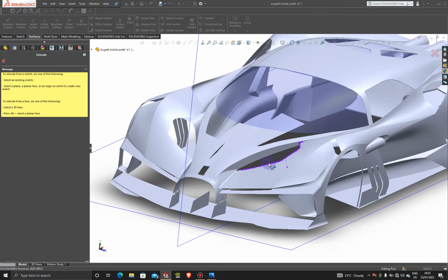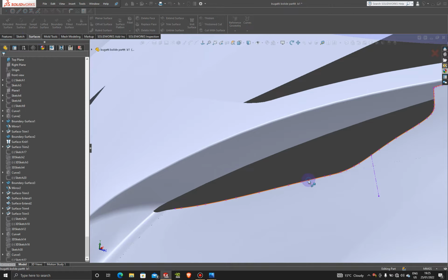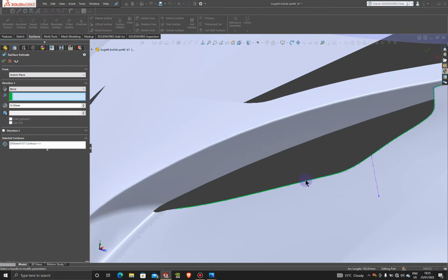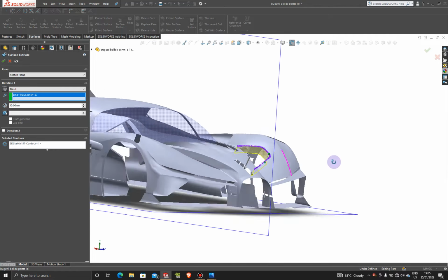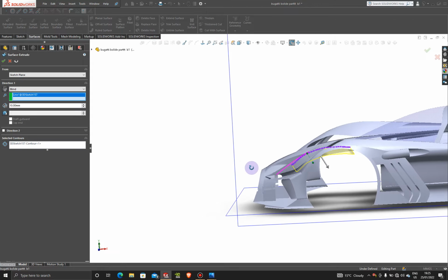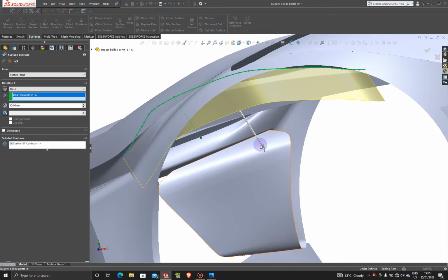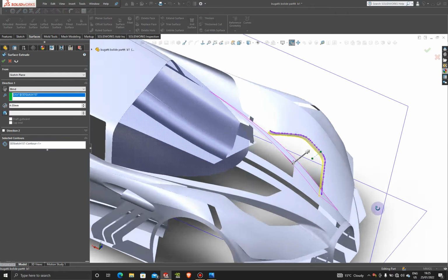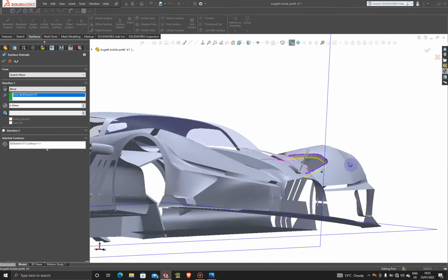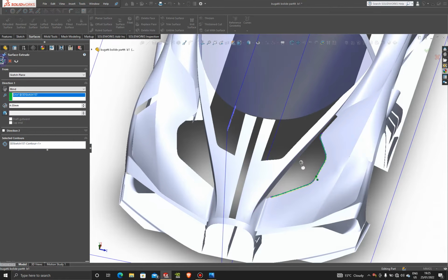All right, so now we're good. So let's select the sketch first. And the direction of pull is going to be this line here. Okay, and then we can just pull this point back so we don't have that much surface here. We don't need that much. Let's have a look from here, and that's good enough for us. Press OK.